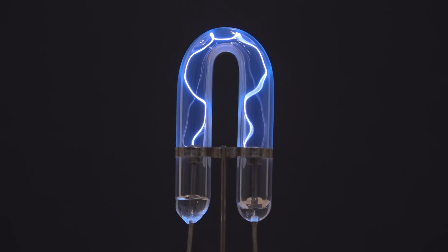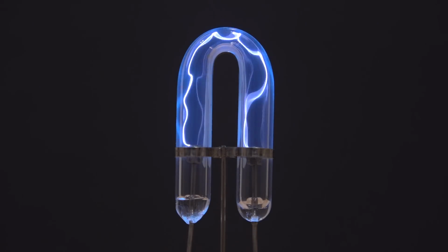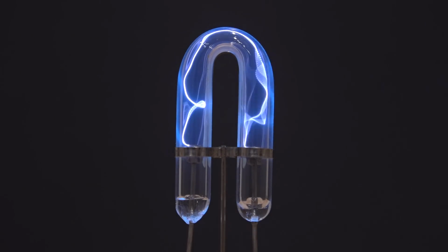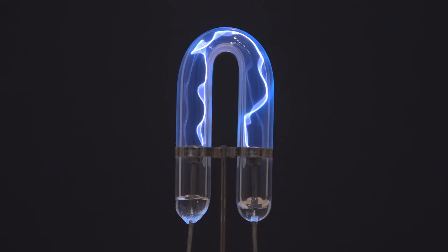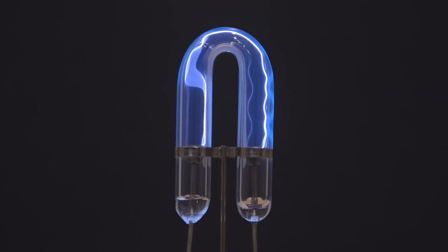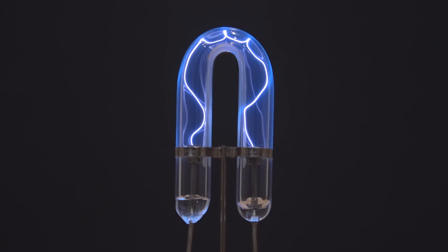about 25 kilohertz, it just stops. The frequency is too high for it to move around, so a particular path, a conduction path of ionized gas, kind of remains maintained, and it stays there without moving. If you hit just the right frequency, it just all of a sudden pauses like that. It doesn't look real. In person, it looks much more interesting, but you can see that it's not moving around anymore. Now think about what's going on. You have a flow of electrons that are hitting this gas, ionizing it, but they're not moving around anymore. That path is fixed because the frequency is so high.